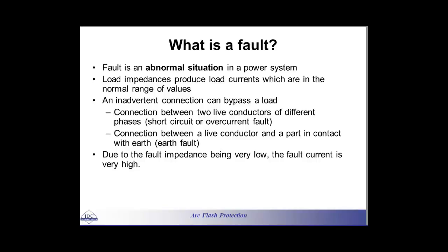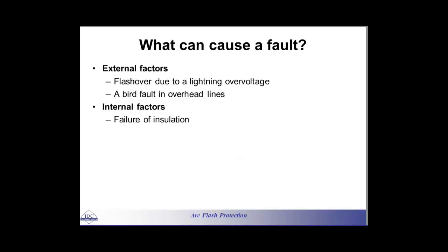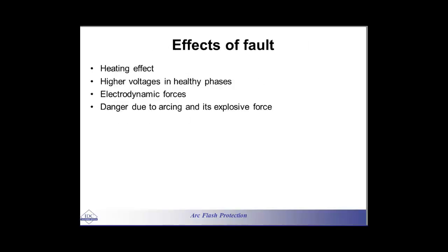So you know what is the meaning of fault? A fault is an abnormal situation, like short circuit, like phase-to-phase, earth fault, single phase, all these things are faults. There are different causes for the faults, like, for example, flashover, like birds coming onto the transmission line or distribution line, a puncture in the cable, or failure of installation, or installation degradation, as we say. Whatever is the cause, there are some effects and consequences, like what?